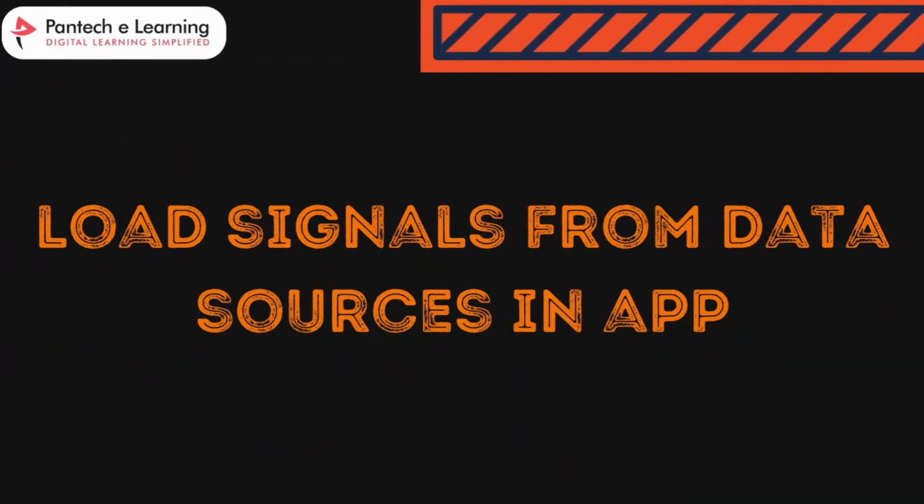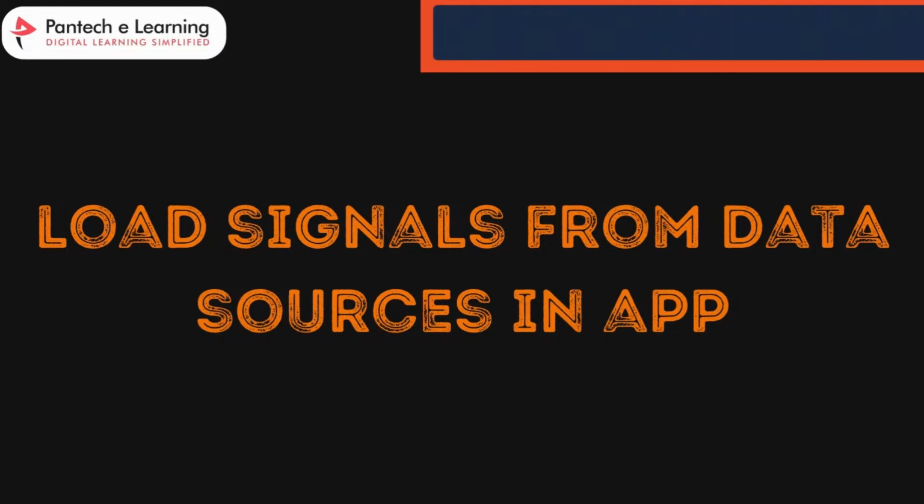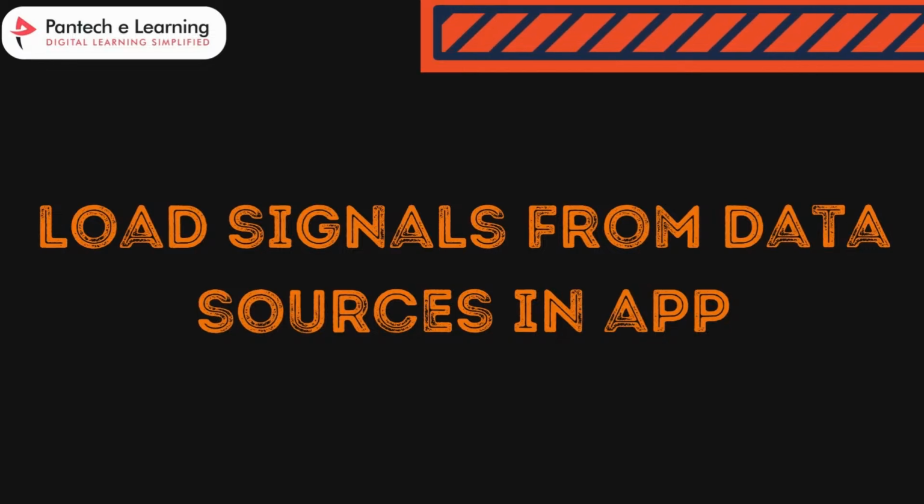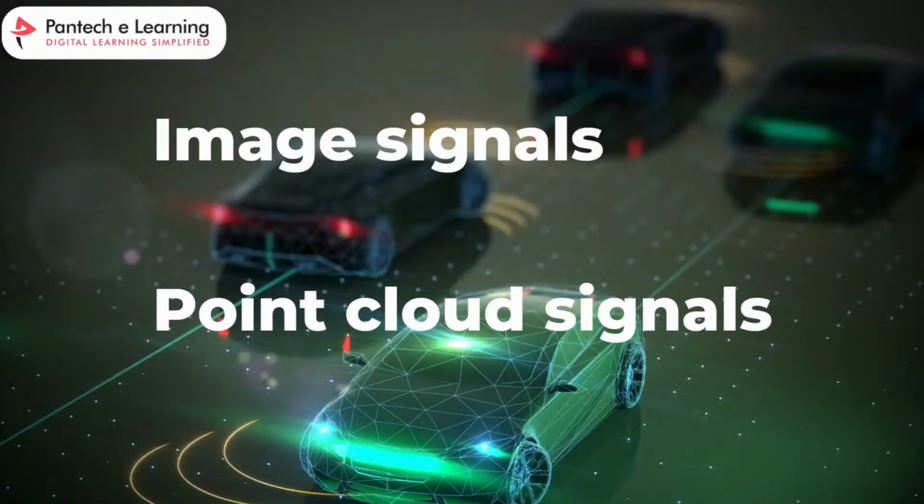The first thing we are going to do in our MATLAB ground truth labeler app is load signals. We are going to load the signals from different data sources in the app. For that, we should first know about image signals and point cloud signals. What does it mean? You can label two types of signals: first, image signals, and another, point cloud signals. Image signals are based on images and can be loaded from sources like videos or image sequences. They represent the visual data captured by cameras or any sensor.